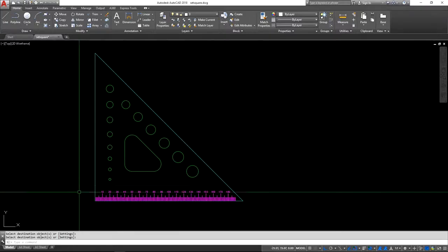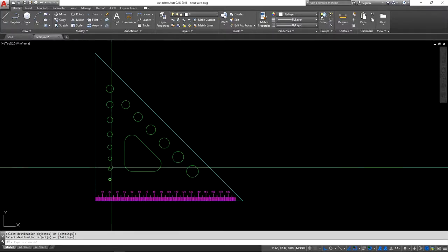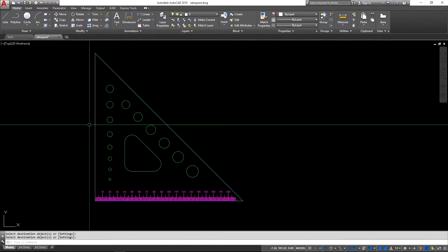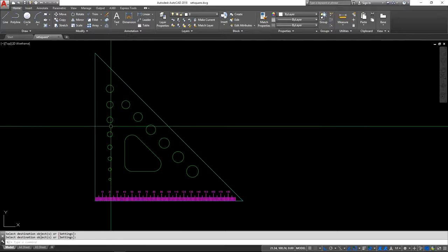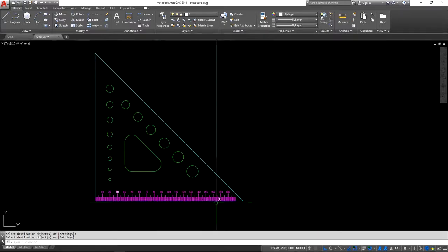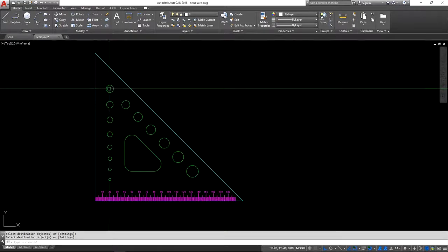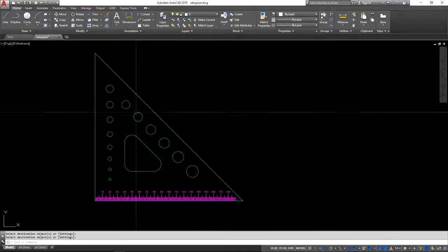Okay, so I've made my way up and back down with all my circles. I just used the offset option. It was much easier. So offsetting the outline in the 20 and then just drawing the line across the bottom, offsetting that up all the increments to get all the intersection points, and then just drawing all the circles in there.